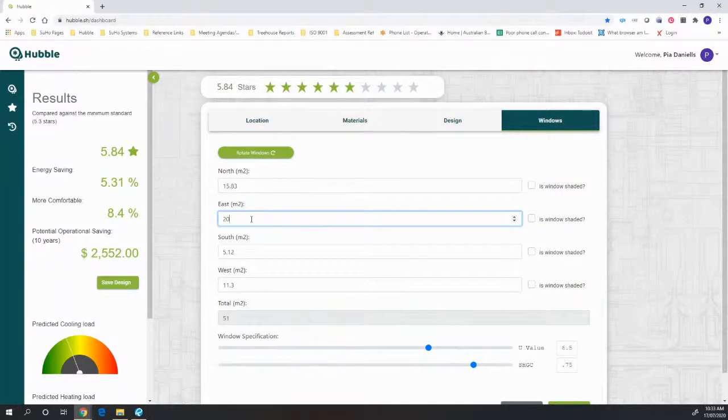North-facing windows are the ideal orientation, particularly if they're in a living area. If they're correctly shaded, they'll bring in the right amount of winter sun while blocking out the overheating summer sun that's coming into the building.